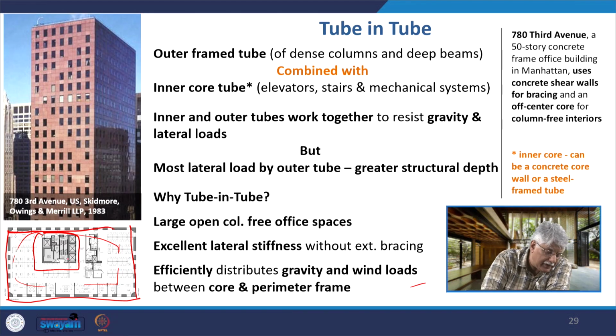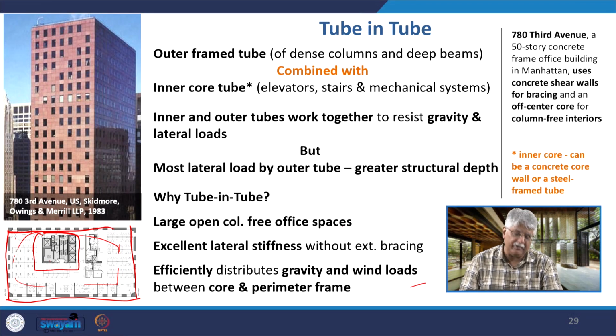Because the core and the perimeter frame are connected to each other, there is a load transfer happening between both of them also, and they work in tandem with each other to maintain the stability of the structure and face both the gravity and the lateral loads.